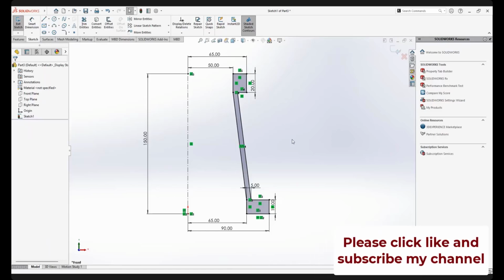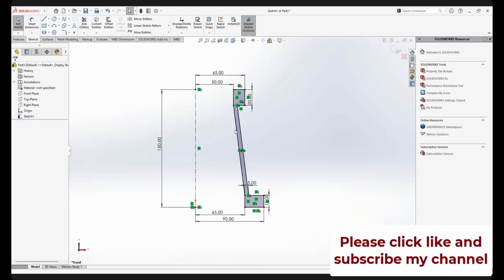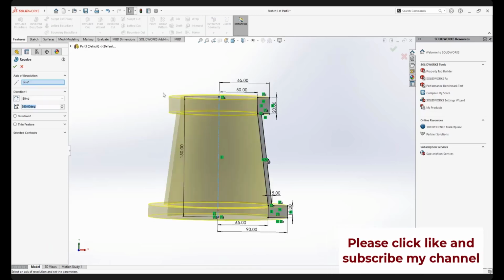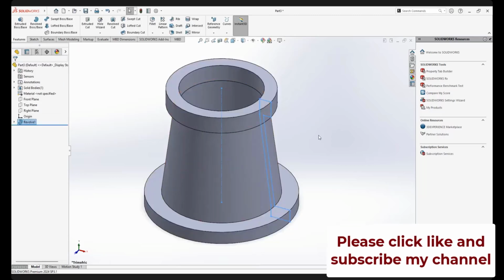If I check and it's a red color under defined, you get 9, 8.5, like that. Be careful about it. You want to get a perfect score, make sure it's fully defined. Okay, now what? Then we will do fully defined. We already have the center line, so we will do revolve. By default, it's already defined. I tell you, if it is not selected here, you select the center line. Make sure it is 360 degrees, so you have this.